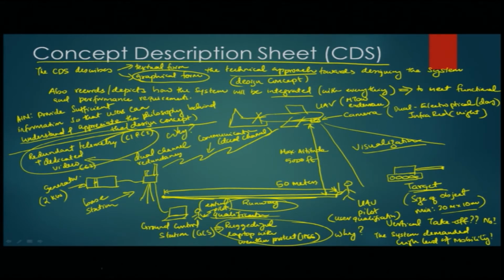You can answer that easily, and the people can appreciate that, no matter what, the aim is to ensure communication with the UAV at all times. So having a redundant communication in two different frequencies and two different channels ensures you that the UAV is communicating consistently with the base station.